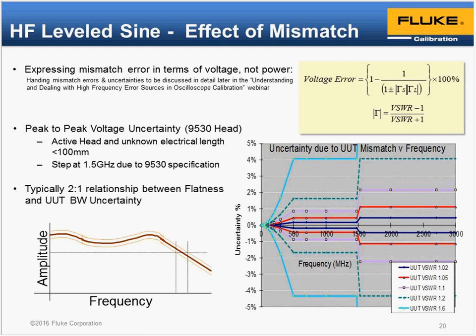As the VSWR increases, as is evidenced in that chart, there is several percent uncertainty. The reason that's important, just to remind ourselves, is we want to look at the uncertainty of the bandwidth frequency, so we have to be able to relate frequency to voltage. We need to know the uncertainty of the voltage and get the uncertainty of the frequency.